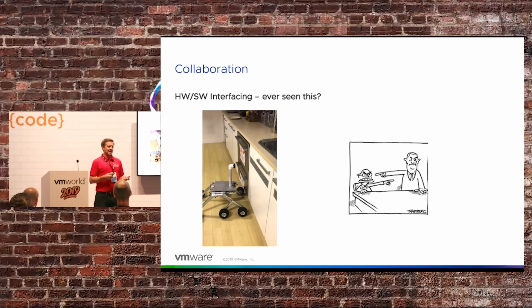We had a bit of a conversation, and I went home that night and rewired the whole thing from sensor to resistors to even components. We tested it, still had the same problem. This was the dress rehearsal issue we had. After a bit more pulling our hair out, I changed the GPIO pin that you saw earlier on the Raspberry Pi. We recut the code because you have to tell it that you're now talking to a different pin, and everything was fine. So we changed everything but the component that was there.